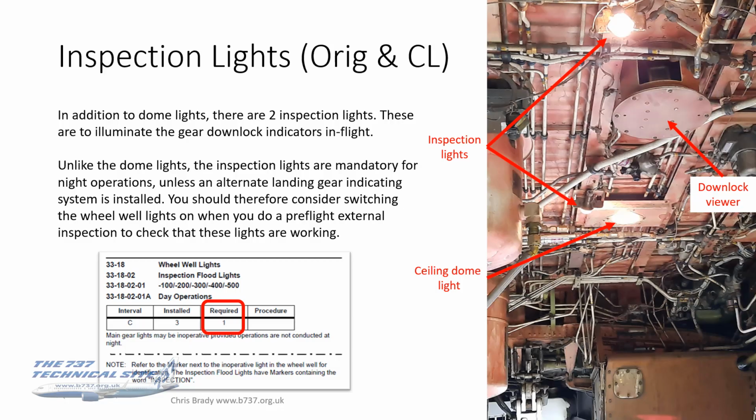Now, again, I've got photos of this in the landing gear video if you want to see that. But unlike the dome lights, the inspection lights are mandatory for night operations, unless you've got an alternate landing gear indication system installed. And freighters often have this.